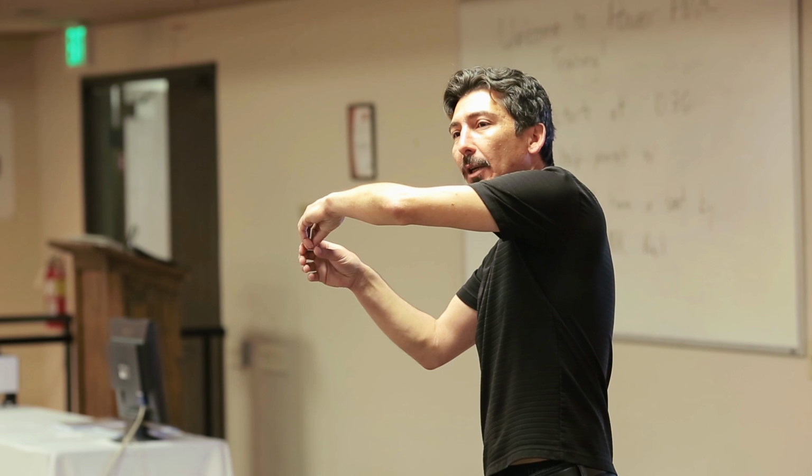we actually define our CAM tables in terms of zones. So you just give the points, and in between there's a third order interpolation of the trajectory. So at each zone, it's like a special learning control law. Let's say I'm in the first iteration. I know the following error. In the next iteration, I can add on top of our control law this error multiplied by a learning gain, and add it on top of my servo. This way, in an iterative, cyclic fashion, it actually acts like an integral action, and it's going to try to minimize those following errors as you go through iterations.